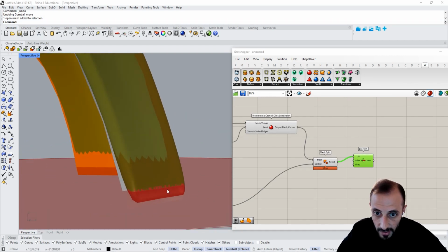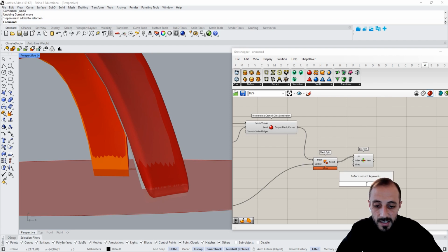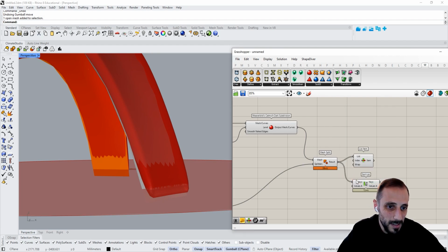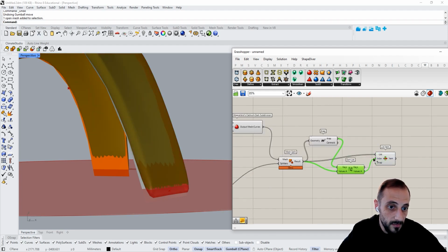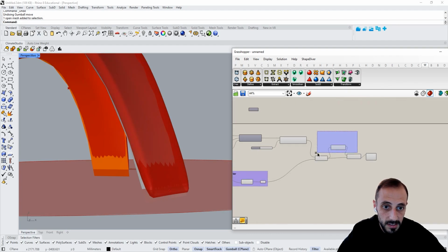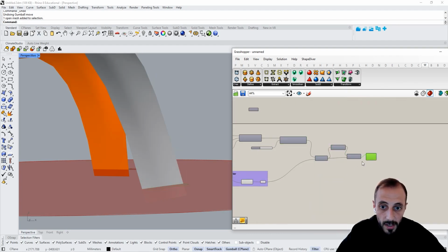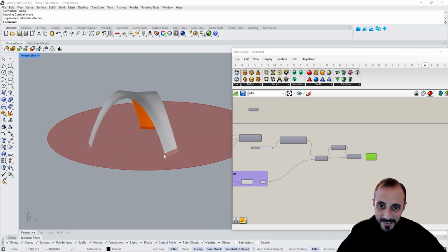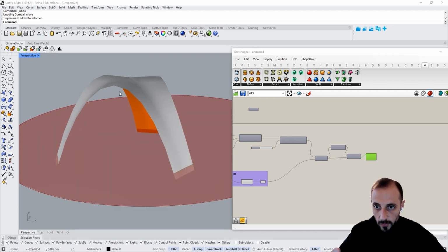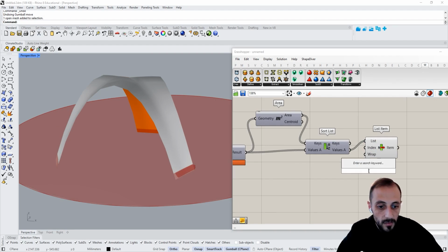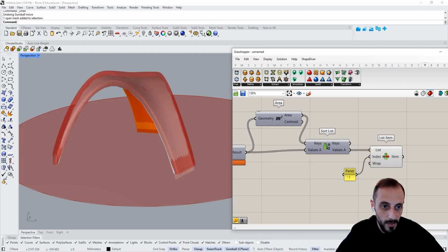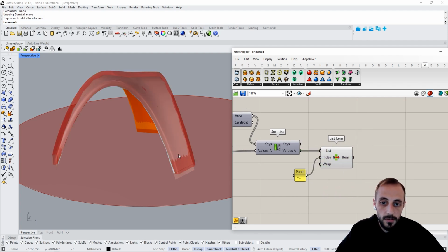However, what we want to have is sorting these meshes based on their areas, so that I can always select the largest mesh, right? And this is my value, but this is going to be selecting, if I preview everything off, this small piece here, because 1, 2, 3, and the 4 is the top largest one. For the index, if I put -1, which will give me a result of the largest one, okay? And this is the mesh I wanted to work with.